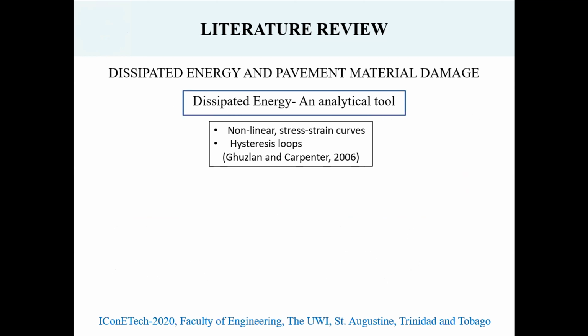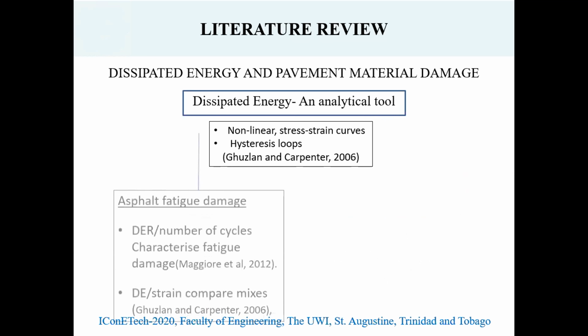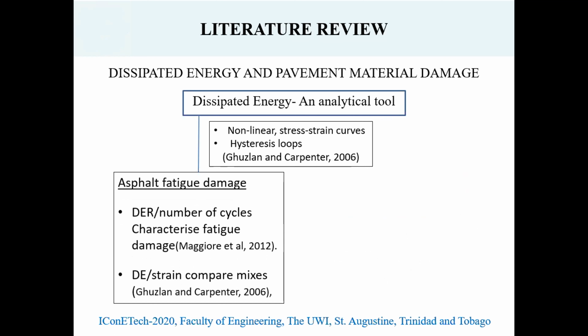Additionally, having been included in some of these previously identified pavement material damage study applications, the dissipated energy concept has established itself as a valuable tool, serving as an indicator of energy release in response to repetitive loading and accompanying irrecoverable deformation. Particularly, damage analysis and dissipated energy have been utilized in asphaltic concrete studies, such as that by Majori et al. for investigating fatigue life, as well as asphaltic concrete studies by Guzman and Carpenter for classifying and comparing mixes based on its damage response.